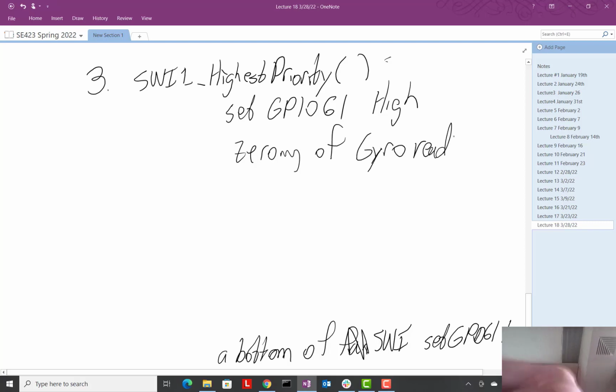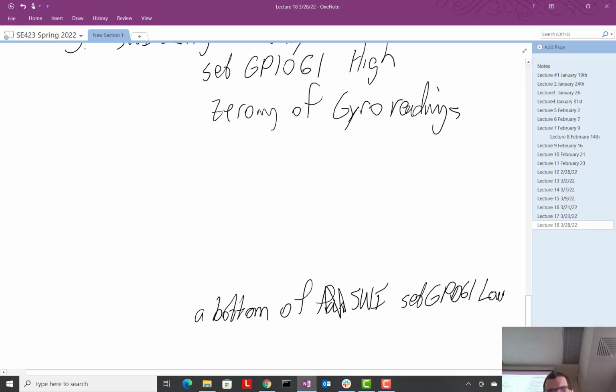So we find for the first 2 seconds we do nothing. For the next 2 seconds we sum up all the readings that we get, and then finally after 4 seconds we find the 0 and always subtract that, don't we? So that we have a nice, at rest, 0 reading from the gyros.